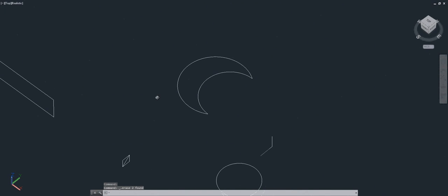can have a good view of the Z, Y, and X axes. I want to extrude this, but I can't just yet. I have to join the two objects, and that's because extrude needs an entire plane, and these are not an entire plane yet, just two lines. So I highlight them, type JO for join, and then I'm gonna join them, which they already did, as you can see. Now everything's highlighted.